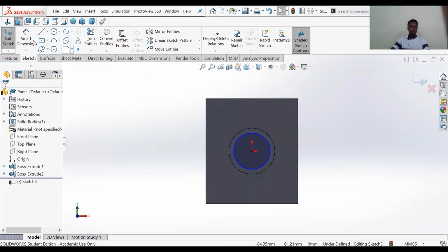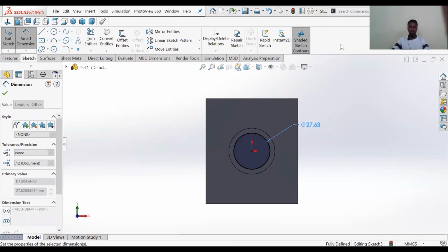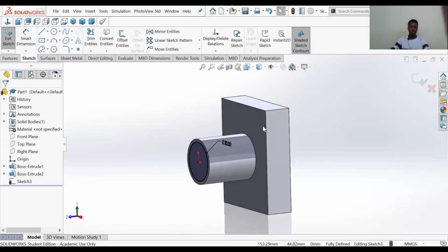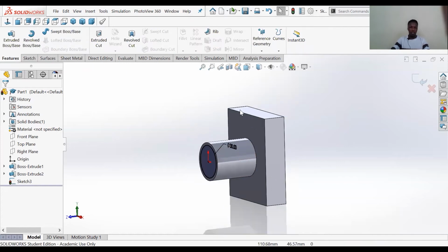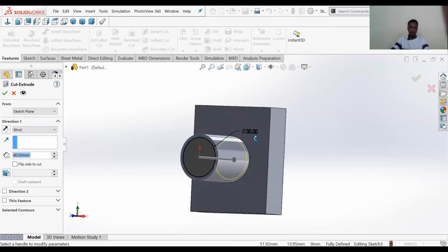and click select. I can give it some dimension, and let's say that millimeter, and click OK. After drawing this 2D sketch on this surface of this extruded cylinder part here, we can remove some material from our 3D sketch by using this option, Extrude Cut, as I've just mentioned. So just select it and we get a preview